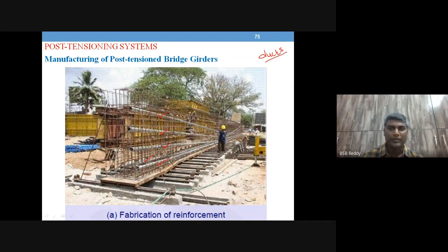Right. So this remaining reinforcement is untensioned reinforcement, or what we call conventional reinforcement. These are just HYSD bars, normal steel that is designed along with the pre-tension steel. So this is what we call a partially pre-stressed beam, because you have both tension steel and untensioned steel.